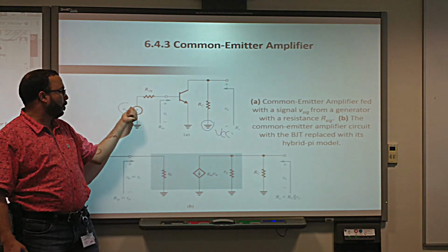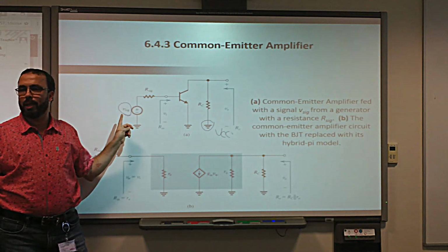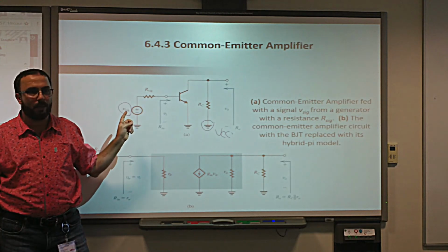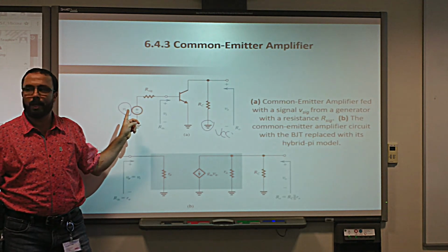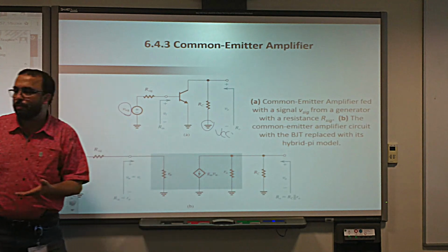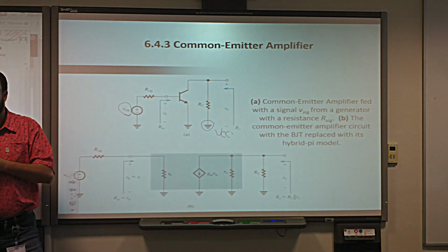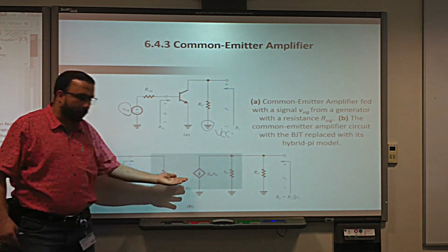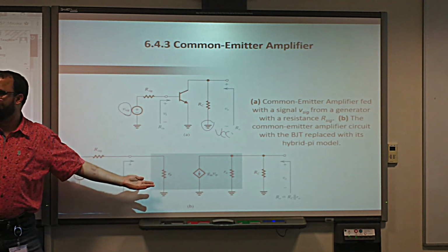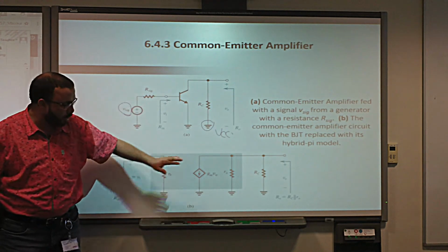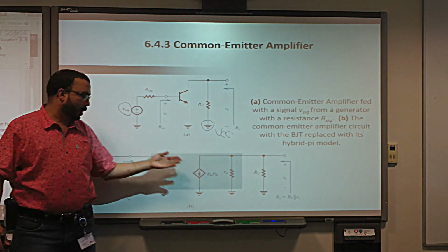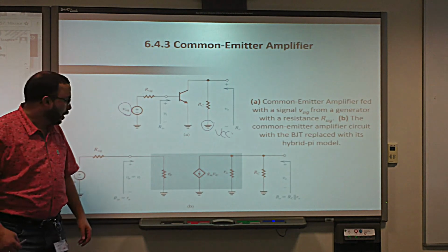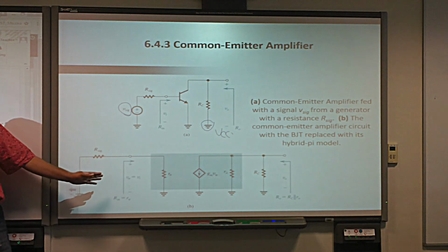That's one more thing, the symbol here for the input signal is small, and that's probably why she said AC. Okay? Good. So the first thing is to make the AC domain circuit. Then after that we put the model of the BJT. We replace our BJT with its model. We know where's the collector, where's the base, where's the emitter, and everything becomes clear. Good. And now we study Rin.